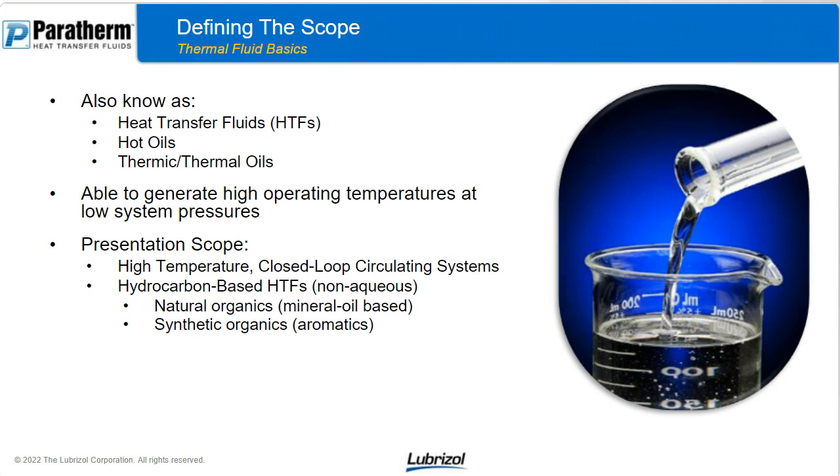Also names for thermal fluid are heat transfer fluids, or HTFs for short. Some industries or folks refer to them as hot oils, others as thermic or thermal oils. But regardless of what you call them, the basic technology and the advantage of thermal fluids is the fact that they're able to generate high operating temperatures at low system pressures. That's a general definition of the technology, but it shows the main advantage.